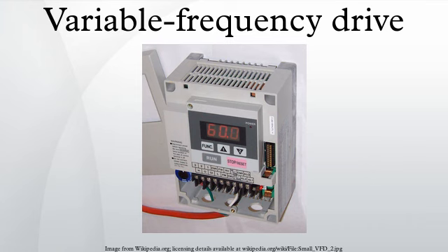Controller. The VFD controller is a solid-state power electronics conversion system consisting of 3 distinct subsystems: a rectifier bridge converter, a direct current link, and an inverter. Voltage source inverter drives are by far the most common type of drives. Most drives are AC/AC drives in that they convert AC line input to AC inverter output. However, in some applications such as common DC bus or solar applications, drives are configured as DC/AC drives.